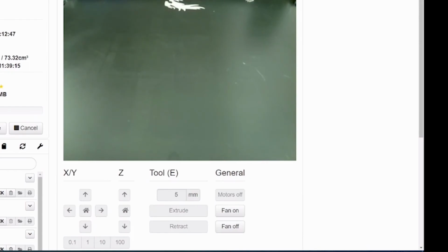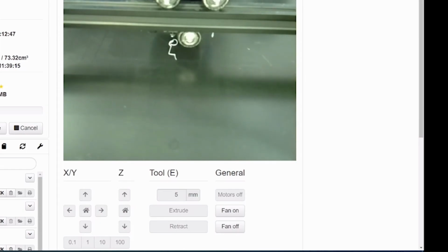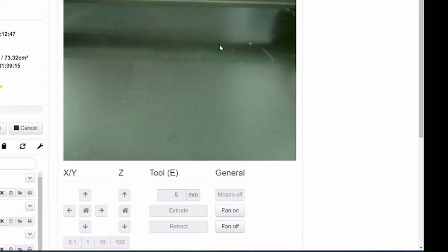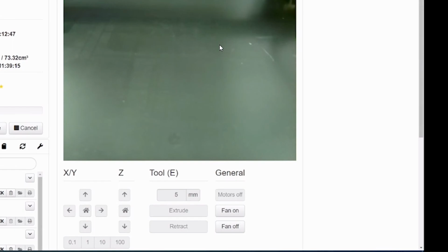we can go to control, and we can see that the system is beginning to operate. The build plate will rise to meet the printhead. You see that little bitty piece of plastic there, and the light comes on. That's so that the system knows where the build plate is in relation to the printhead. And then it will prime the printhead. And that's it. When the model is finished, just be sure to allow the system to cool down.